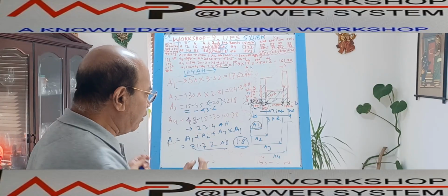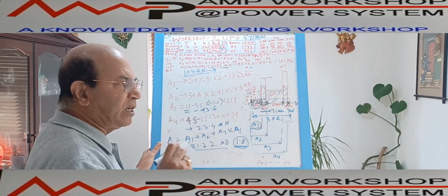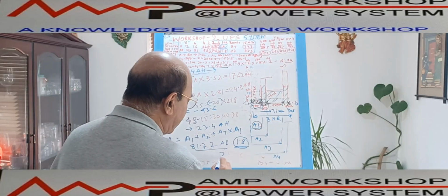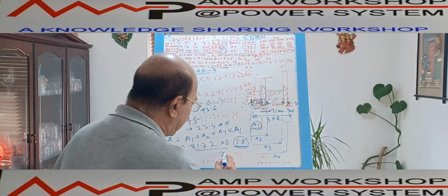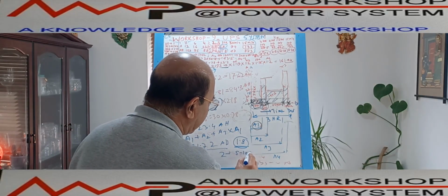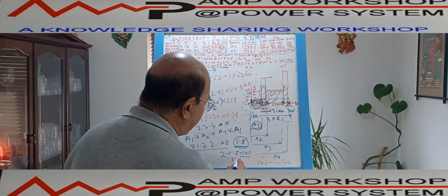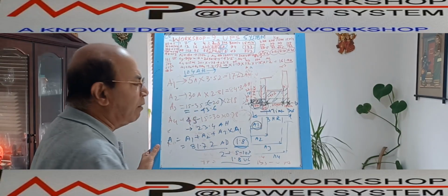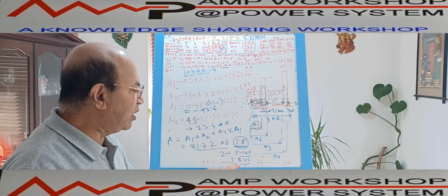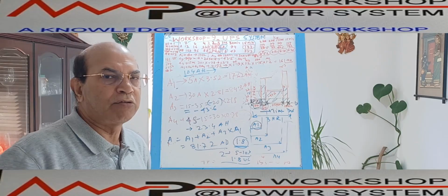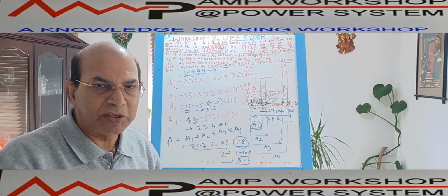The battery nominal voltage, as already discussed in the previous section, is 2 volt. So if the battery drops from the nominal voltage by 10%, how much is that? It is 1.8 volt. After that, we don't allow the battery to be discharged. Now when we limit the battery discharge at 1.8 volt, it will not be able to deliver its entire capacity.